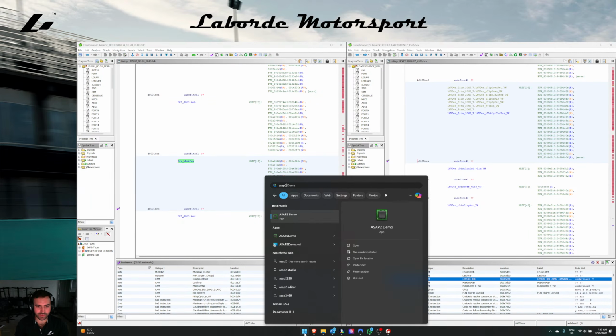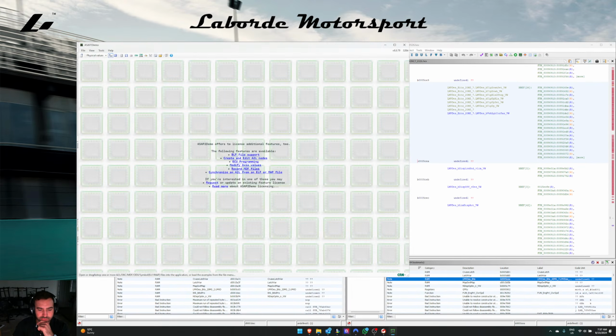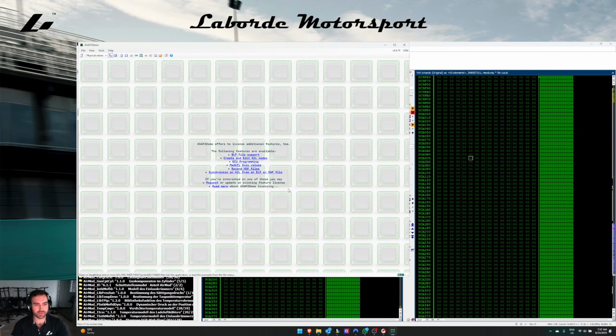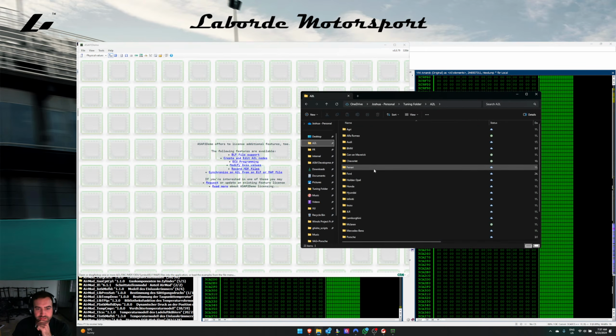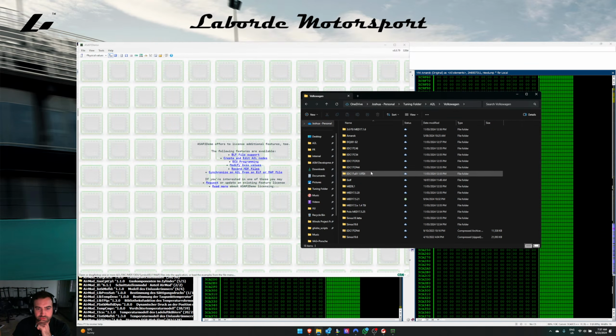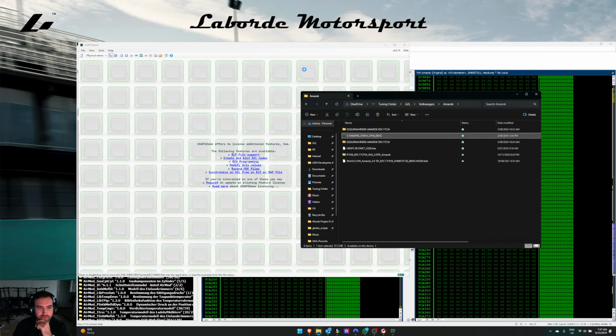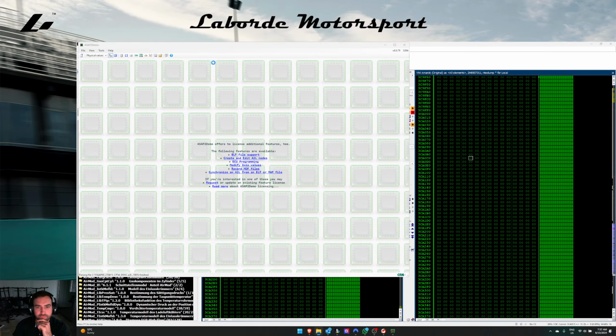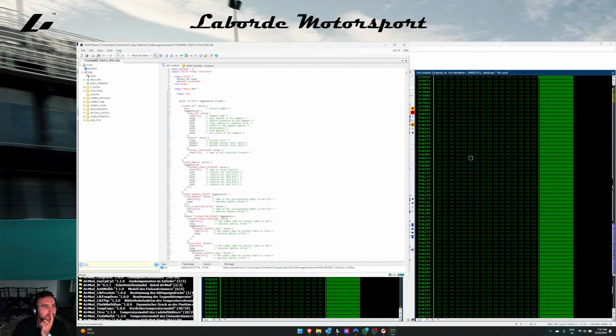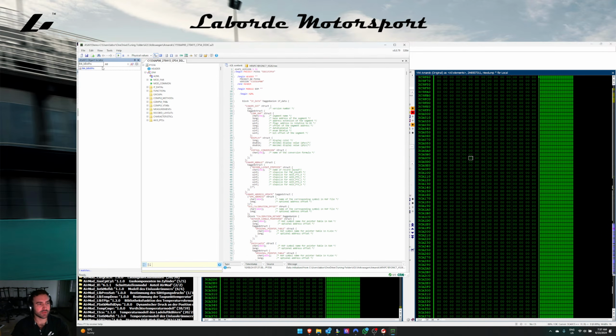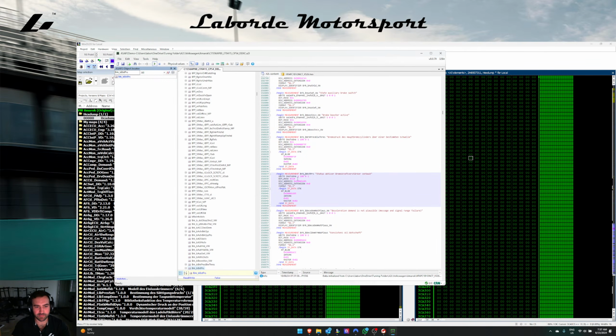I'm also going to open up ASAP. Or I might just search for it. No, I'm not going to do that. I'm actually going to do it this way. And if I go to Volkswagen, I go to CP54 or just Amarok. I then bring that in. And then we're going to go to the search bar. We're going to type in this variable that we're after, and we're going to see here that the bit mask is 10. Okay, a bit mask of 10 is a bit position of 4. Okay, I'll explain that to you.